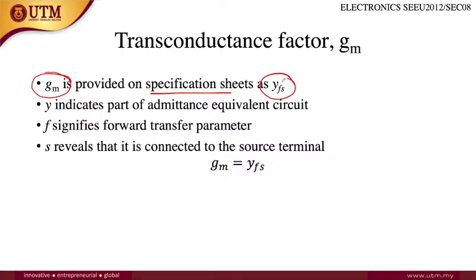So what is the meaning of YFS? Y indicates admittance, equivalent circuit. F signifies the forward transfer parameter, and S means it is connected to the source terminal. So GM is always equal to YFS.